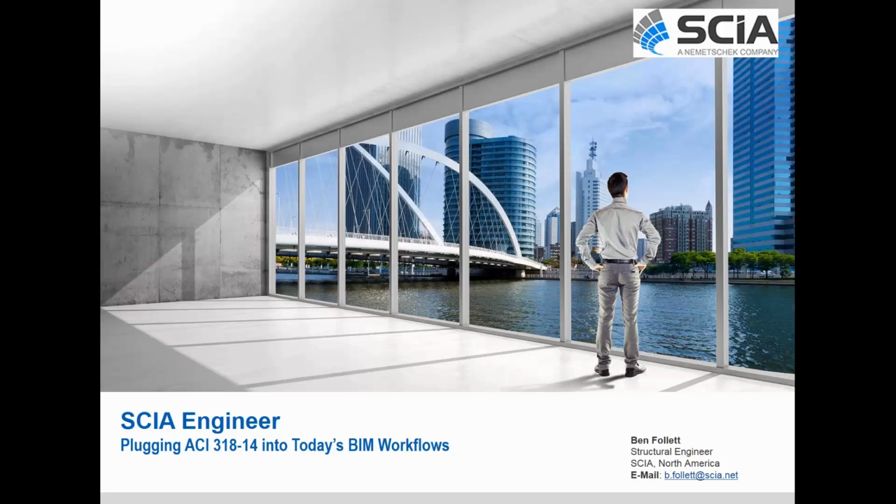It's exactly as you say. The design part of the software actually lets you define if there is a weak story and amplify the shear forces during the design according to this soft story effect. Also, one could actually model the actual building, meaning if it has a soft story due to CMU infills, he could model the CMU infills with cell elements that are not participating in the design, but actually create the stiffness effect for the whole building.